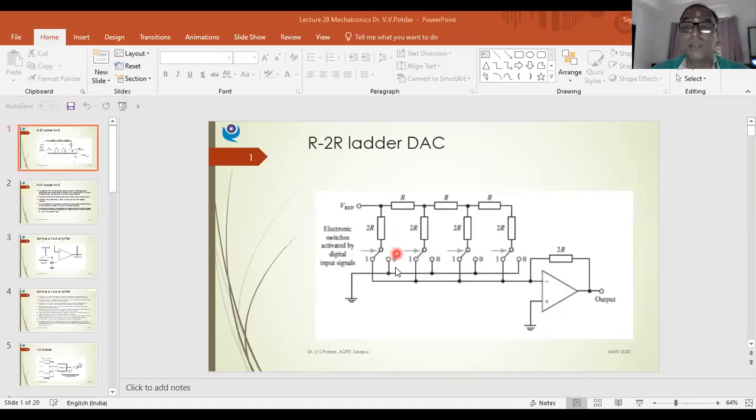Now this is the feedback. This should be very clear: your op-amp doesn't come all alone. It will always have a feedback loop. Wherever you use your op-amp, in whatever form, whether as a summer, subtractor, multiplier, integrator, differentiator, whatever it is, there is one feedback loop. So this is the standardized notation, or symbol, for your op-amp. Remember that. The output is fed back, and this op-amp will be used either as a voltage follower, a summer, a subtractor, or a comparator, whatever role it has to play.